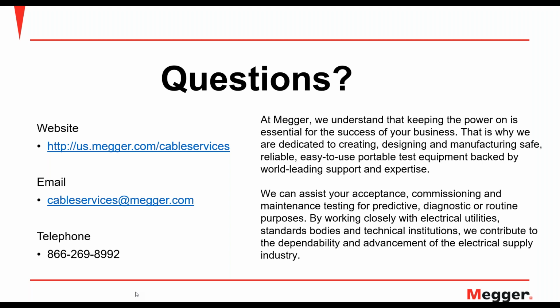So DC high pot was found to be, and this is in the IEEE standard itself, destructive to the XLPE or plastic cables. It basically stressed the insulation and could cause cracking and was destructive to the cable. Now, DC high pot is still commonly used on PILT cables, where you have the paper, lead, and oil. The idea is that the oil there is sort of self-regenerative and alleviates some of the stress that would be caused by performing that test on, say, XLPE cable. So we're not abandoning that. It's just that for the majority of cable now, VLF or withstand testing at 0.1 hertz is the way to go so as not to cause any damage to your cable. So DC high pot is definitely still a thing. It's just more predominantly seen on PILT cables.